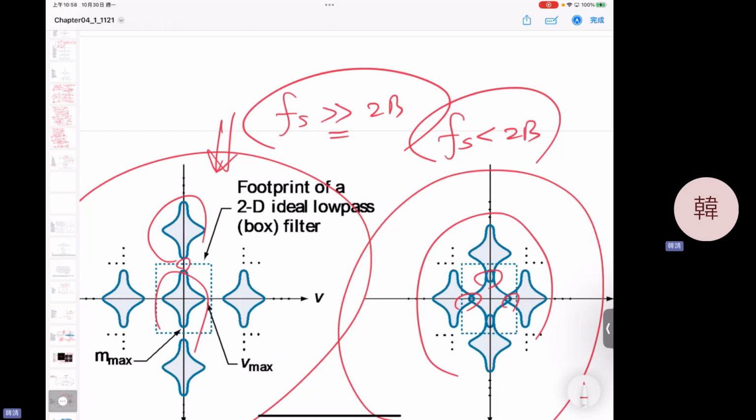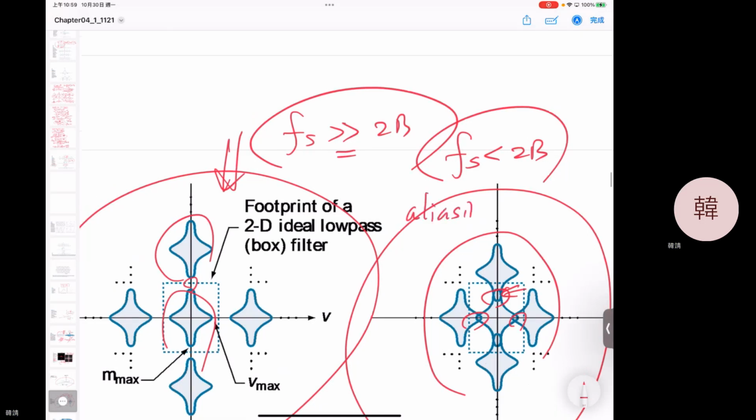That's not good either. You'll lose some of your higher frequency information because they overlap and add up together. So no matter what kind of processing you do after, such as image filter design, your original image, due to the wrong sampling process, has already been caused aliasing effect.